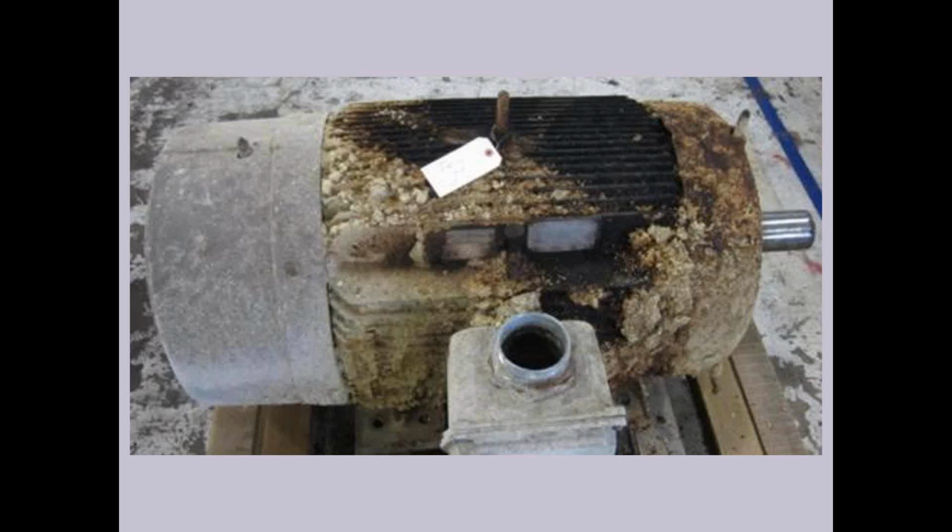Here's a motor that failed in a process at one of my customers. Now, why did this motor fail? Well, we can see it had product buildup in the vanes. It wasn't letting air get across the motor. The motor eventually overheated, so I don't remember on this one whether the windings actually failed or the bearings failed, but this motor overheated and failed. Again, we let this happen. This motor could have been cleaned weekly, and we might have extended that motor life 2 to 3 to 4 times.